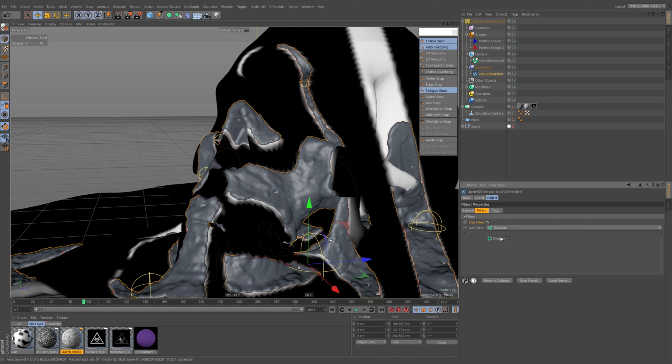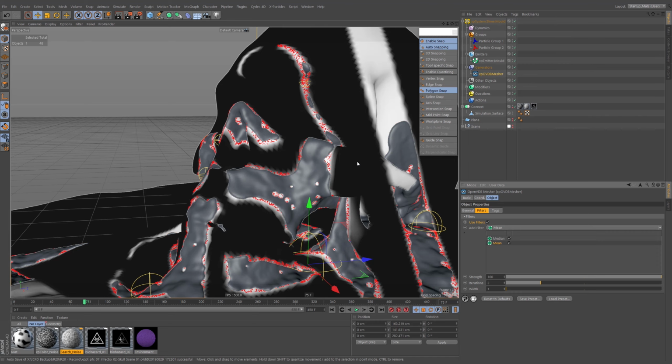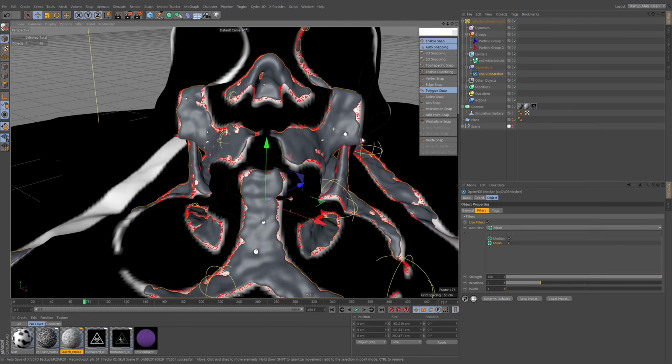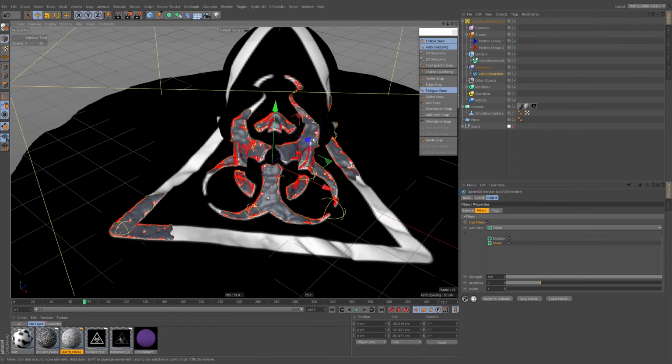Like this is a median operation. That's probably fine. And the other one I like to do on these kind of meshes is just a mean. And the mean I'm going to have do a few iterations. And there you go. Now we're getting a much smoother mesh. See that? Now, is that going to be a problem in terms of coverage?